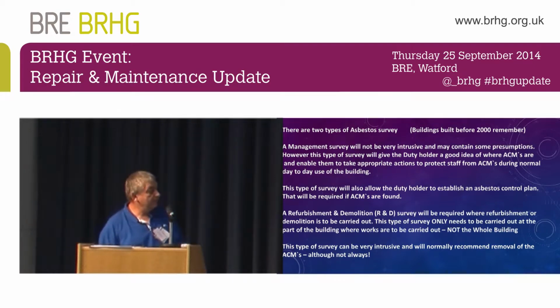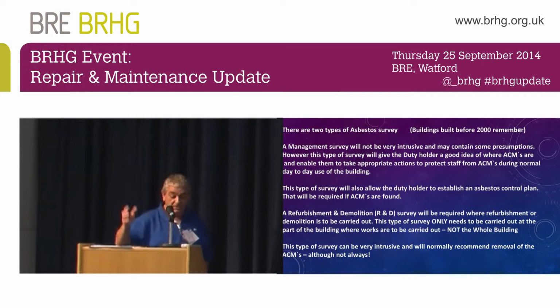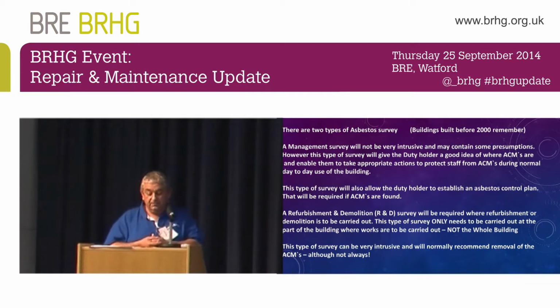What scares a lot of people off this is that they just carry on doing the works without the refurb and demo survey anyway, and work from the management survey. Totally illegal, shouldn't do it. They do that because they think, oh, refurb and demolition survey, I've got to have every floor done. No, you don't. You just have to have the refurb and demolition survey done in the area where you're going to work.